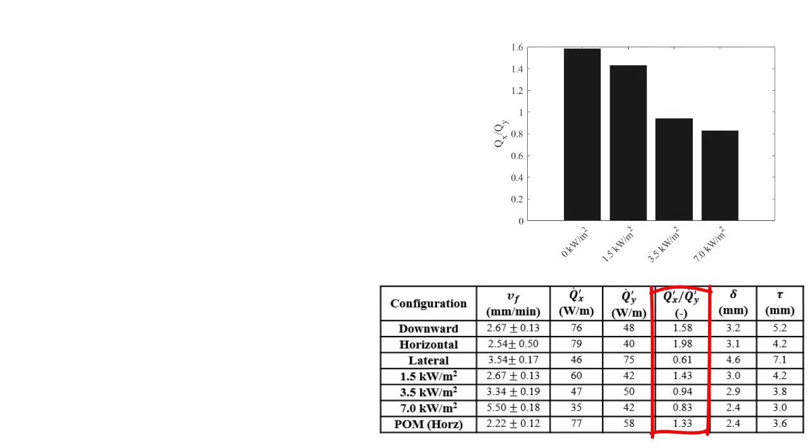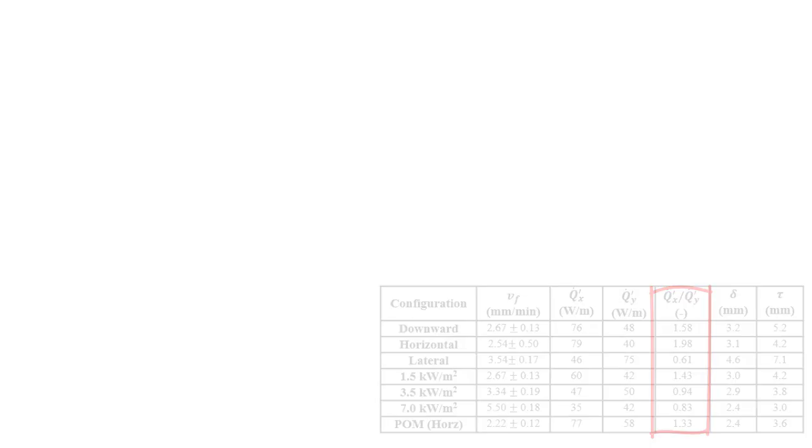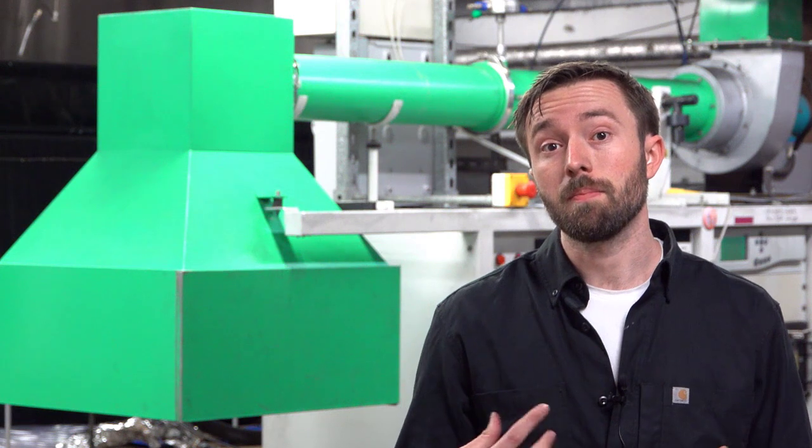Another important observation for these results is that in no case observed here do either the solid phase or the gas phase components become negligible, meaning that in each case that we see here, these mechanisms become increasingly or decreasingly significant, but in no case can they be completely ignored. Now, the associated paper to this work dives into more details on these results in particular, but this study effectively produces a method by which researchers can quantify the solid phase and gas phase heat transfer contributions looking at the flame spread process using relatively simple measurement techniques.